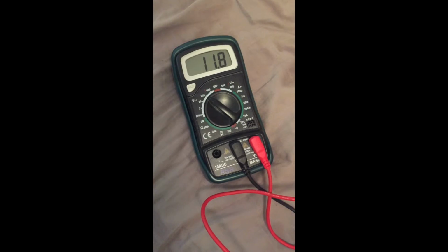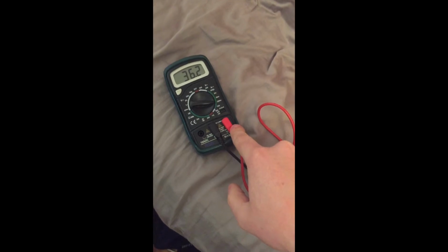which can be varied and changed. Alright, to measure current, you want to measure in series, so therefore you want to break the circuit. I've got a resistor here on a breadboard, so we've got the positive lead connected to the positive of the multimeter, and then the common ground goes out and connects to the resistor on this side, and the negative of the battery comes to the other side.